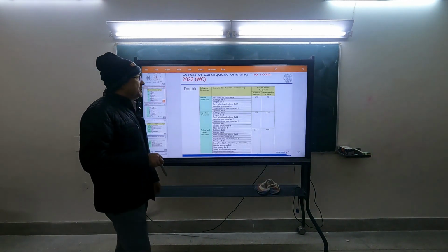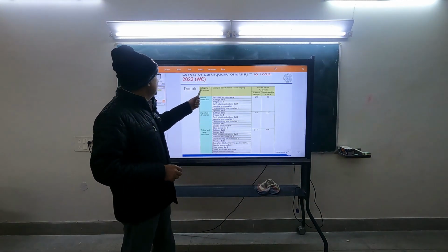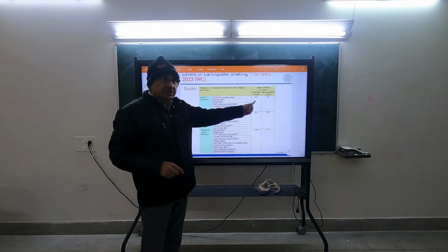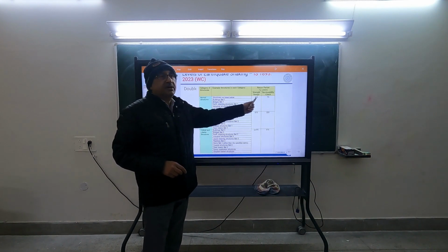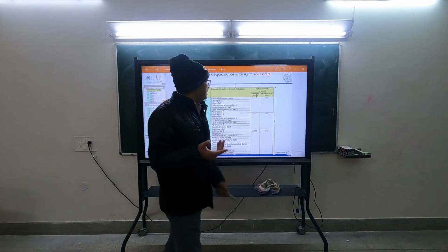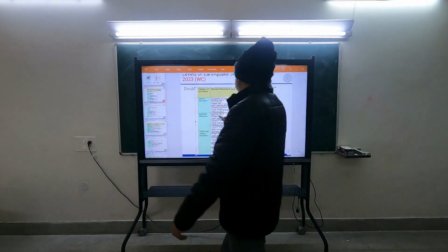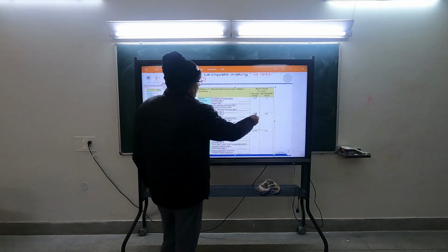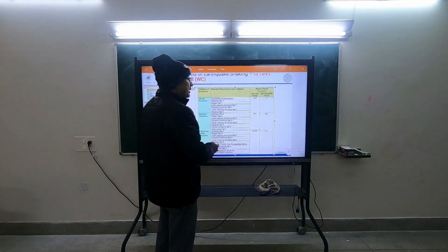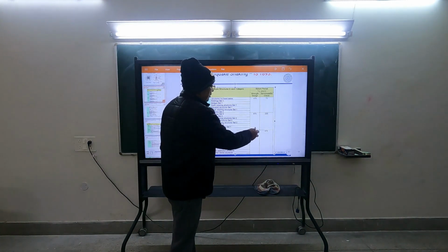So these return periods for serviceability check and strength check vary for different structures. Ordinary structures, normal structures, strength design, that means limit state design, will be done for 475 years. That is DBE. And serviceability will be done for 73 years, 50% probability in 50 years. Important structures, it is 975 years and 225 years. And in case of critical and lifeline structures like hospitals, it will be designed for MCE.